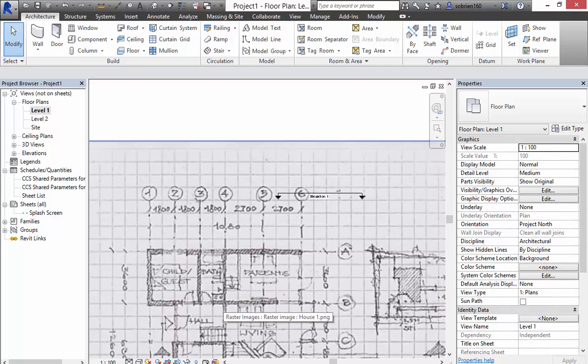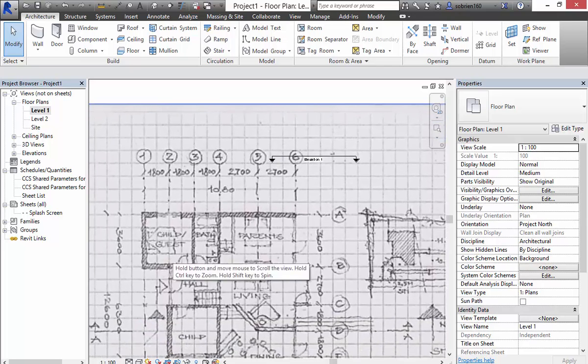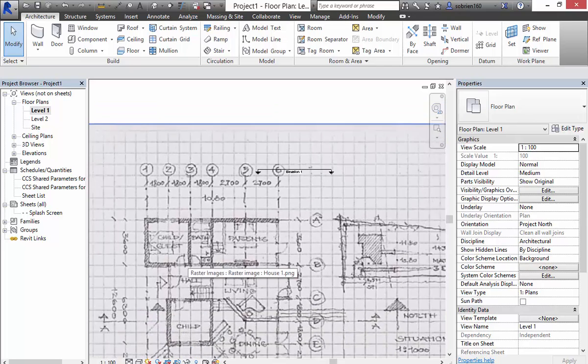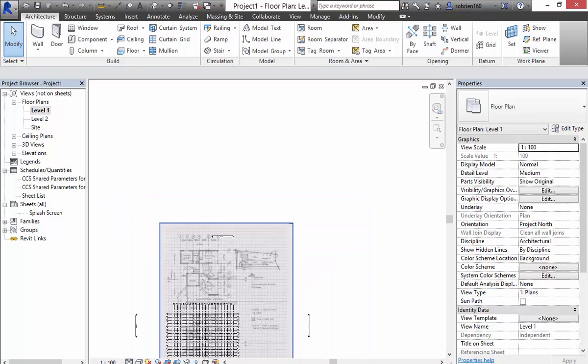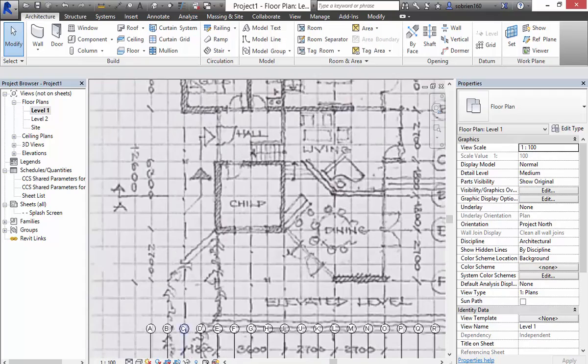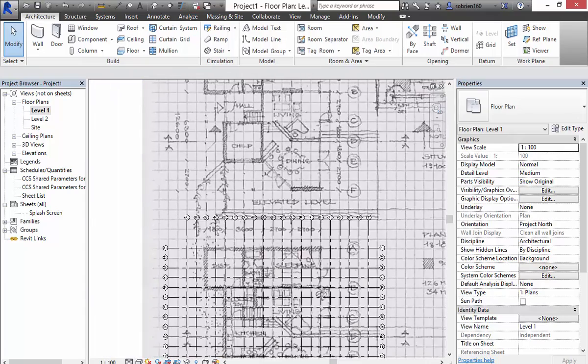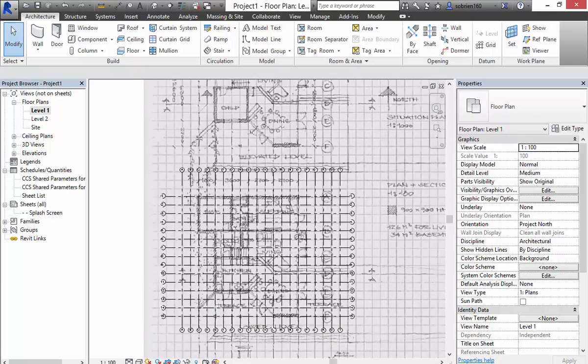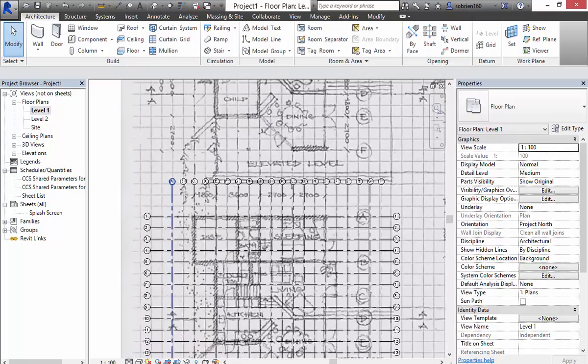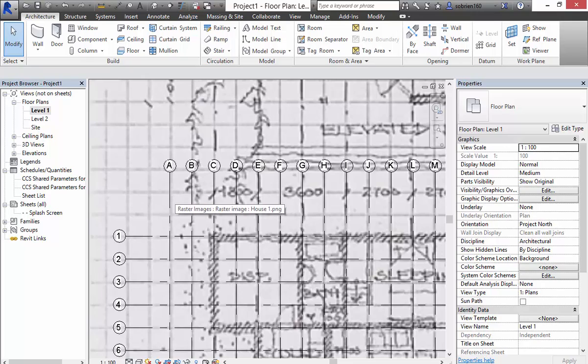We just want to use it to space the house out in such a way that each room is a multiple of the module. So we don't need that much structure in it. We don't need a structural element every 900 millimeters in a house, unless you want to withstand some kind of bombing situation or whatever. So what I'm going to do is turn these grid lines into a different type of grid line, a more background type idea, so it actually has the same impression as the squared paper.